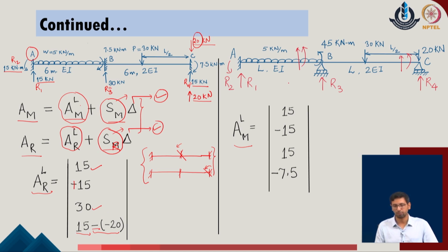In the similar manner, now we can move to identify the reactions with respect to the given system fixed ended part as well. The directions of the member forces are defined AM1, AM2, AM3 and AM4. Now, in order to define these forces, we will come back with the same idea which we initially defined, that these member force reactions or member force components will be having their directions and magnitude same as the reactions which are appearing at the fixed end supports which are nearest to these joints.